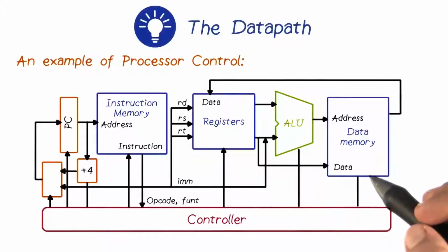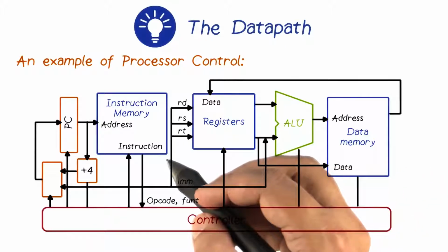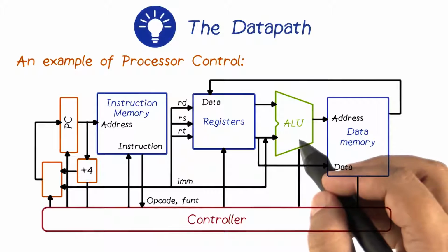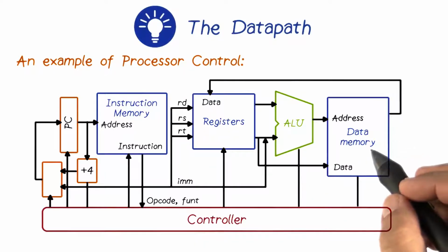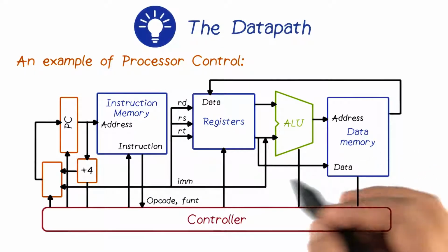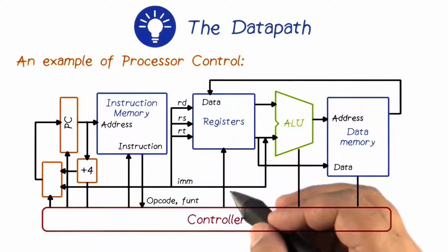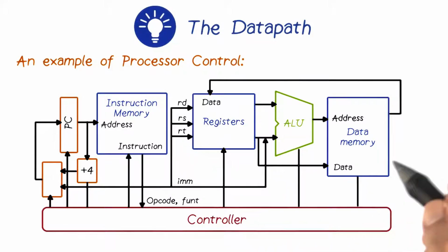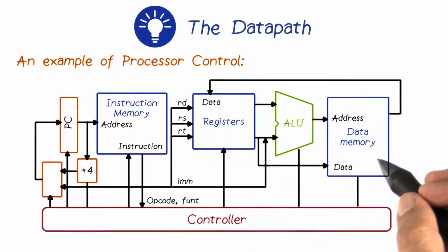So what else needs to happen inside a processor apart from the data path for storing the data in registers, to process it in ALU, and to read and write out of memory? Well, somebody has to coordinate these actions, and that part of the processor, which is really important, is called the controller. What does it do? It makes sure the data is latched properly into the buffers and latches and is read properly. It also makes sure there are no hazards. It also coordinates the operations of the I/O devices and also the memory.